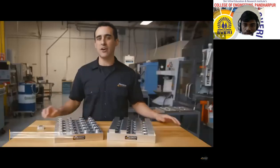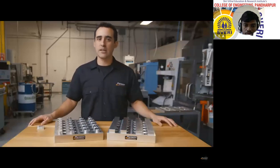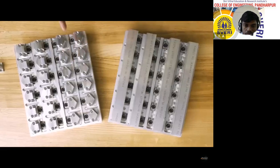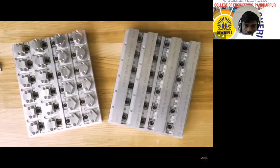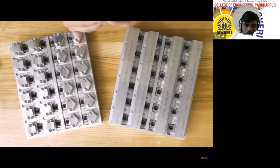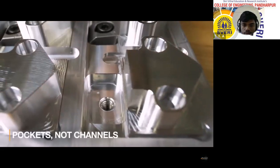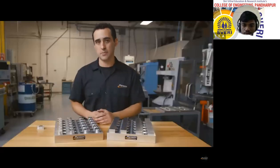We're also using these rocker style clamps in the 3/4 width, and we're using 1 per part. Now, the manufacturer of these clamps usually illustrates machining a channel for these clamps, but don't do that. We don't recommend slots because the material in between the clamps actually helps strengthen the pallet from the forces that want to spread the channel apart. Instead, simply machine a pocket for each clamp and then pattern it across the whole pallet.